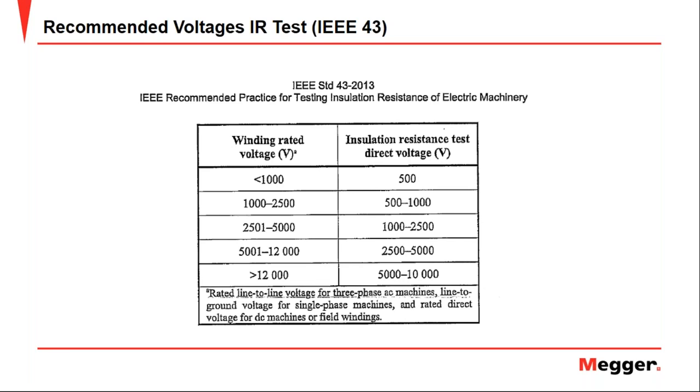So we are measuring the temperature in the case of the motor, but that is not the temperature of the winding. If the motor was running, we have to take the reading of the temperature in the casing of the motor, and we have to add about 10 degrees Celsius in order to know what the real temperature of the winding is. But as we said in the webinar, that is not in the standard. That is just a common practice, a rule of thumb.